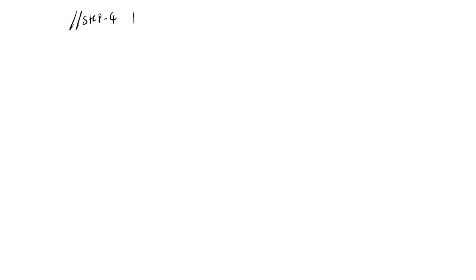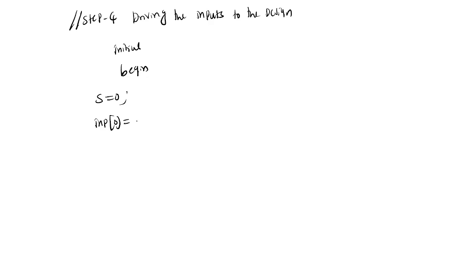Next, step 4: driving the inputs to the design. Driving the inputs to the design means what? Here, initial begin. I am giving s equal to 0, and next inp of 0 equal to 1, and inp of 1 equal to 0.